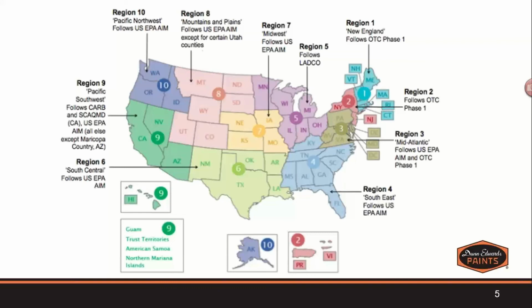So for example, here in the Pacific Southwest, since we don't really see blizzards or hurricanes, we might see snowstorms in some areas, and hot weather is a dry heat. We really tailor the ingredients and the actual performance of the coating to meet the weather that we see here. Our buildings are also different in some ways. We utilize a lot of stucco, whereas on the East Coast, there's a lot of brick or masonry. So all these products, and especially when you see regional companies, they really specify on the climate and the building structures that are going to be using these coatings.